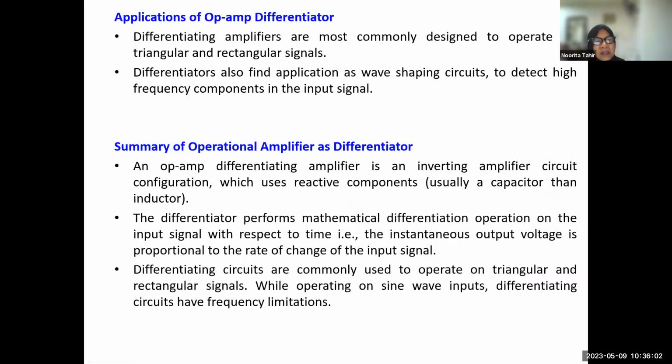So where do we actually utilize the op-amp as a differentiator? When we want to operate on triangular and rectangular signals, and also when we want to detect high frequency components in the input signal.